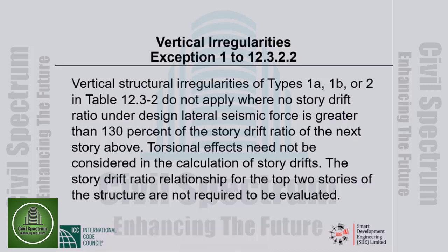Torsional effects need not be considered in the calculation of story drifts. The story drift ratio relationship for the top two stories of the structure are not required to be evaluated.